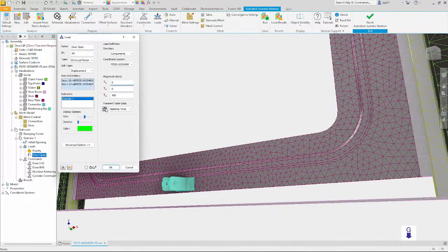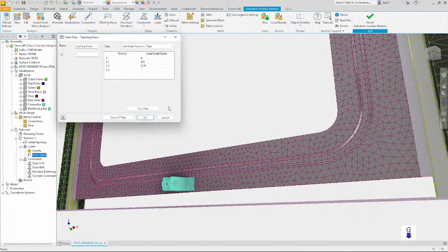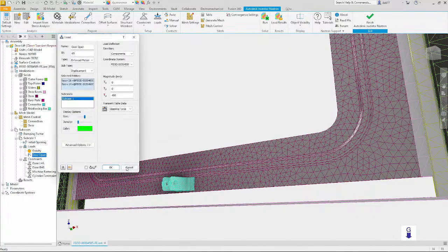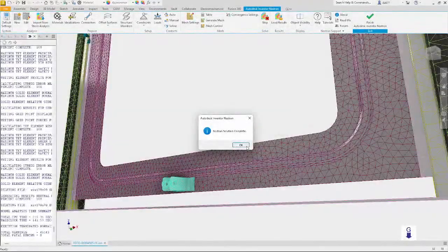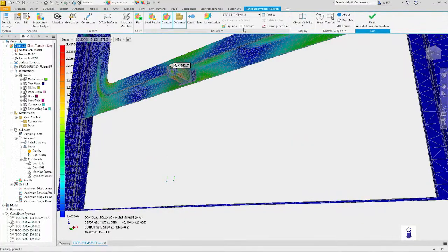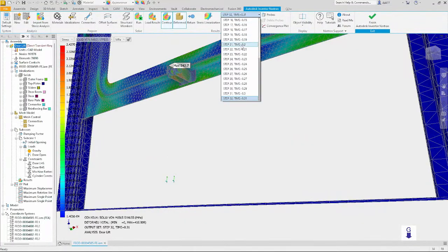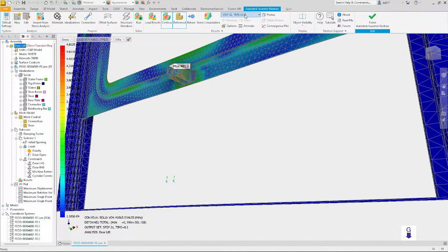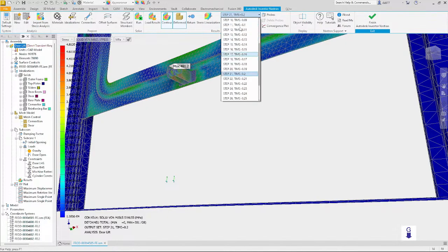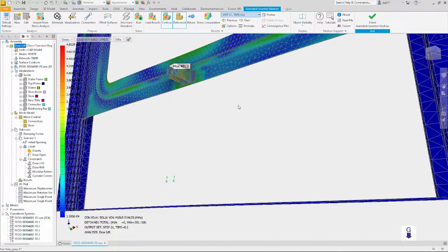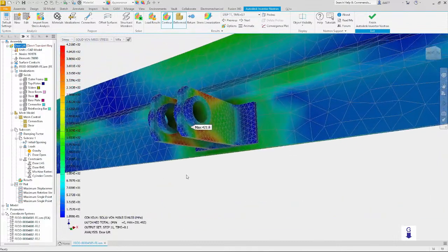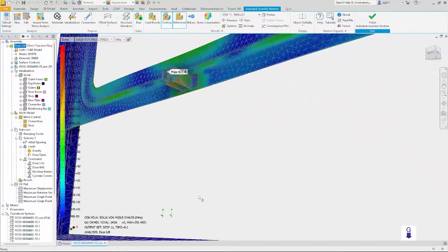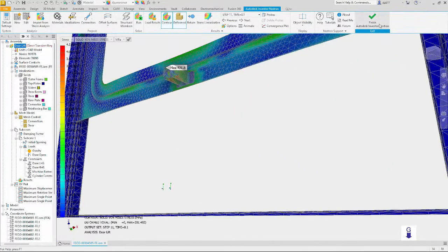So here's the door opening. It's going to lift 400 millimeters. We have time steps to show the acceleration or deceleration of the door, and the simulation is run. In this case, it's run over a certain period of time, so we get time steps, and you can view at different time steps what the stress looks like in the object. And we see quite a high stress, max 421. It was a little higher earlier, so this component might be an issue.